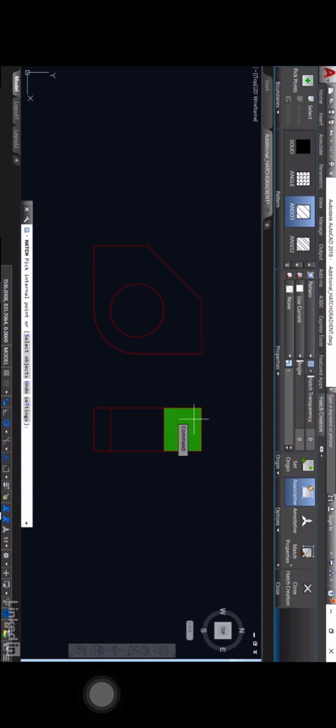Now, if I hover over here, you can see it almost looks solid. There's a very, very fine, grainy effect there. What that means is the hatch scale is a little bit too small. So I go up to the Properties panel here in the Hatch Creation tab, click inside the scale box, let's make that say 10, and press Enter. Now, when I hover, I get my preview, and that's a perfect hatch. I might even make that a little bit smaller, actually, maybe 5, and then press Enter, and there you go. There's a nice hatch there.